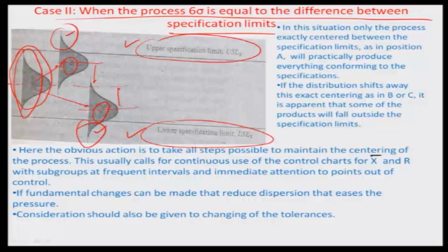So obviously either you change the process control by making this a little bit tighter, so that you can have the spread lesser, or alternately you can think of changing the specifications, if there is a lot of factor of safety which has been put in the original design, so that still the process can be within control. So there are various ways to execute this.